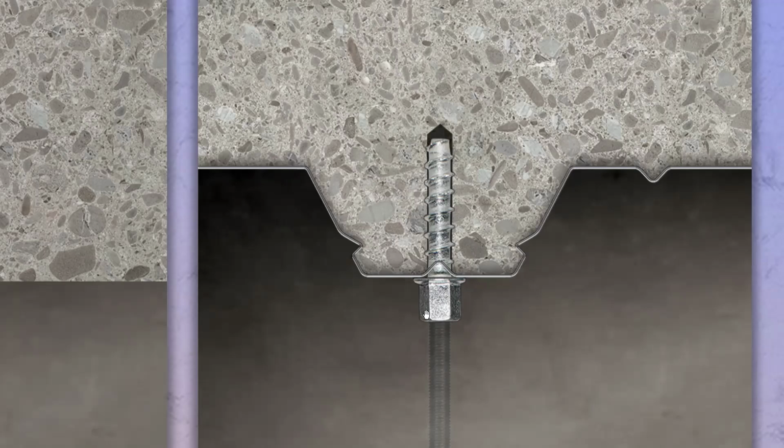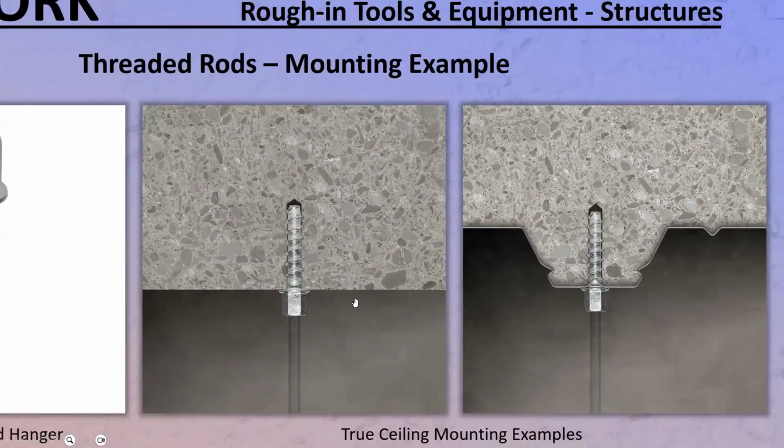Then the steel drill bit is going to hit the concrete and get dull after a few uses. So you're going to go through a lot of drill bits, and it's not easy to drill a hole in that steel because it is hard. Then you change the drill bit, and with a hammer drill, you drive the drill bit into the concrete, and then you can drive whatever device you need.